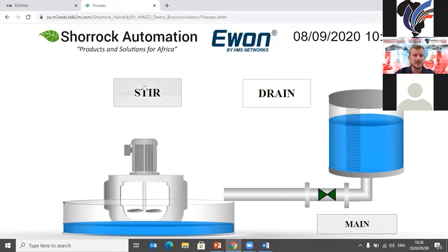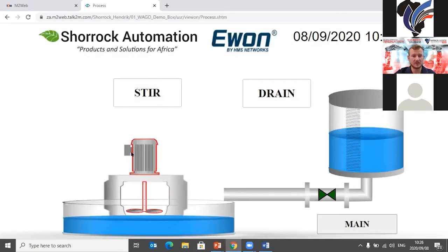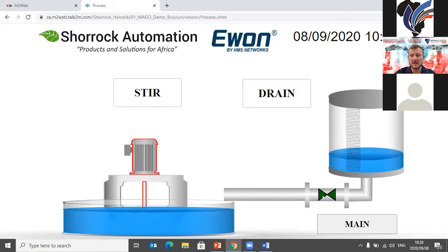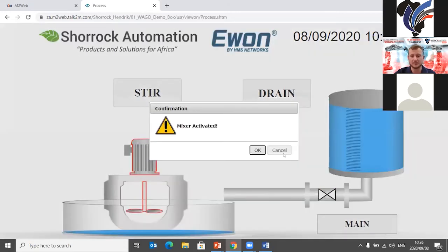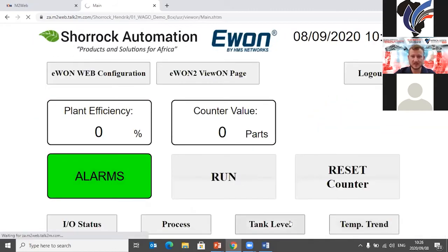to B. And then I can also switch on a stirrer with some indication. This could be a direct online motor or contactor that just pulls in to put on a stirring motor. And I could actually get some feedback from a solenoid valve to show that it has in fact opened. Okay. Just another brief example, tank level.